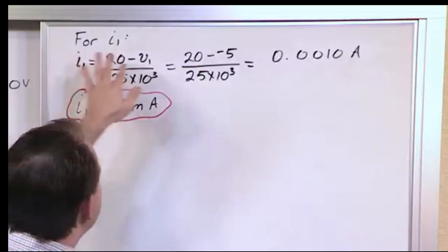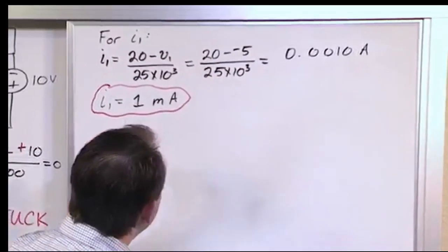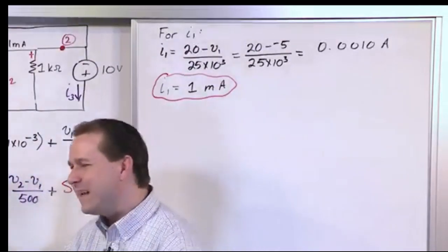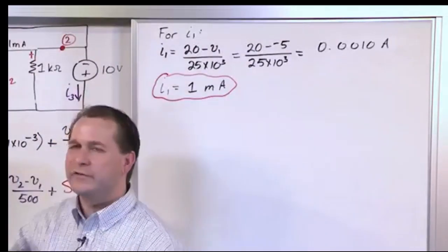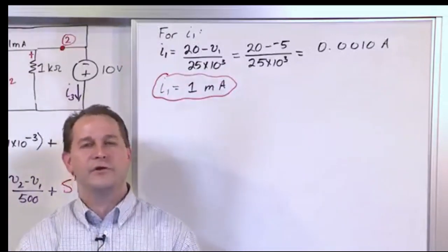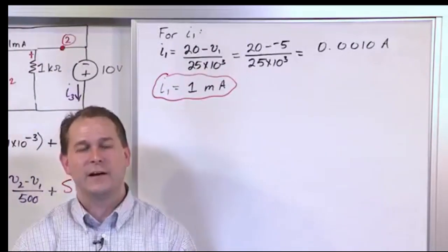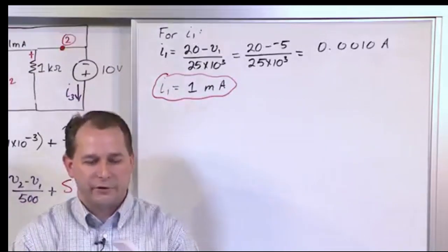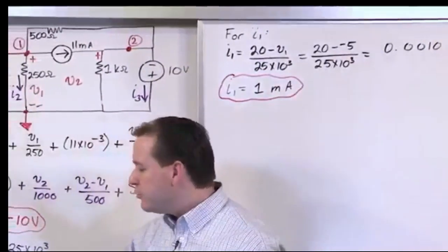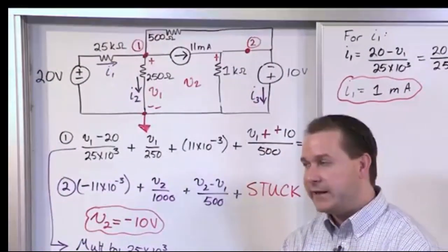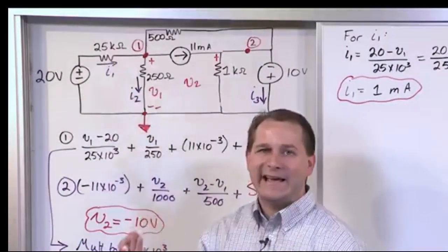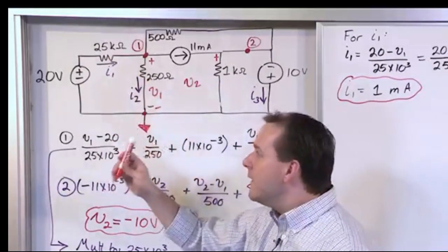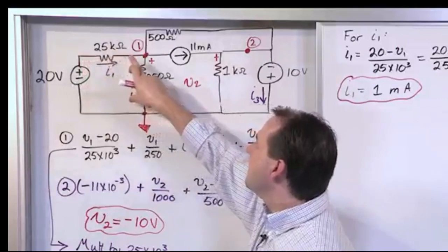Now, this whole subtraction business, it gets people confused. A lot of times whenever you solve the problem, you have a negative node voltage, your current is drawn in the circuit opposite of the way that you solve the node voltage problem, it can get confusing. You need to separate the two, right? When you solve your node voltage problems, you pretend the current is leaving the node and you get an answer. Then, separately, whenever you try to calculate a current as given and drawn in a problem, you need to assume the current's going this direction, right? So, to do that, you subtract this minus this.